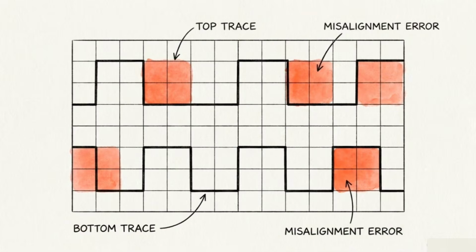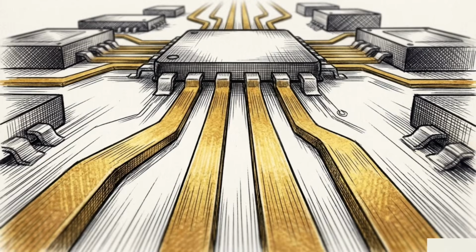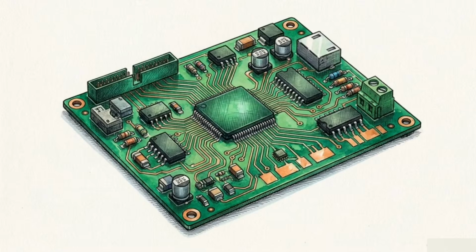If a developer selects phase 1 when the peripheral expects phase 0, the receiver will sample the data line at the wrong moment, and every byte received will be entirely corrupted. SPI provides maximum throughput. It is the optimal choice for high-bandwidth components, trading pin efficiency for dedicated hardware lines and raw speed. Everything discussed so far assumes the clean, controlled environment of a printed circuit board.